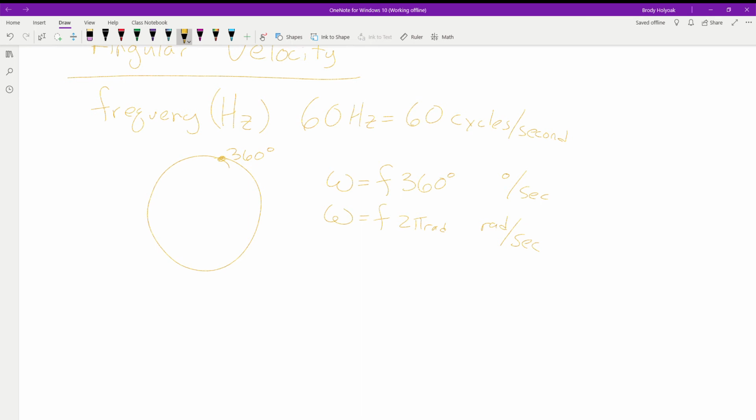And we can work in either direction. We can be given how far we traveled, and we can solve for the frequency we're moving at. Basically, how fast are we going? The reason we want to know this is when we get into motor controls. Because we're working with stepper motors, we want it to go to a specific position every single time. Think of it with a robot arm. We want it every second to reach over, catch a pie, move it over, and set it on the conveyor belt to get it going.